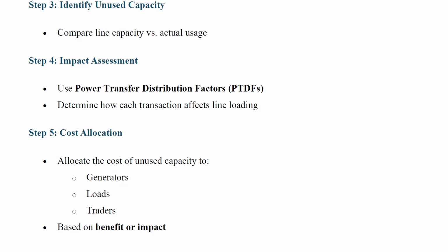After that, the skin effect will be more, because the conductor is ACSR, aluminum conductor steel reinforced, and the outside of the conductor will become polished. Then you need to replace those lines. That is also there. So that impact assessment also we are calculating, and based on that we are keeping some cost.